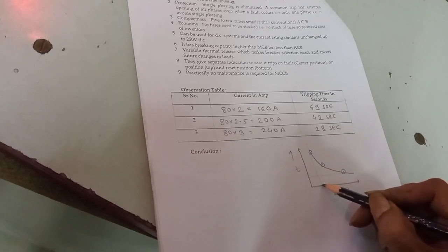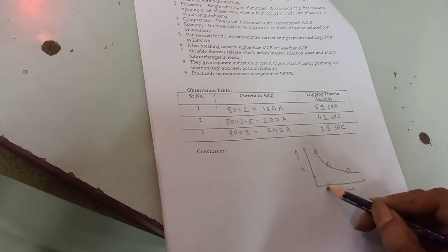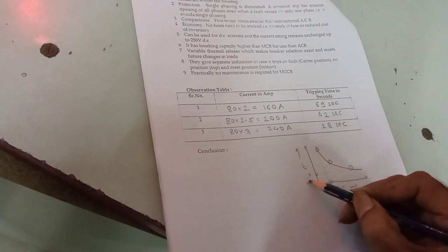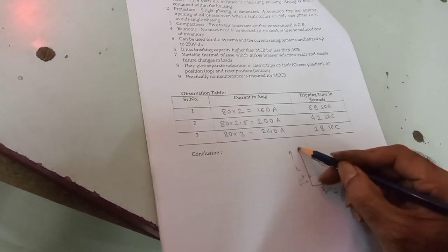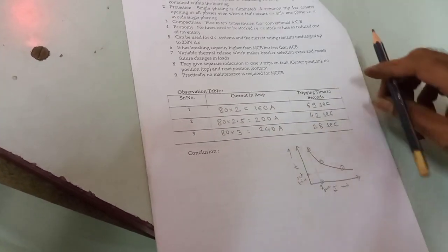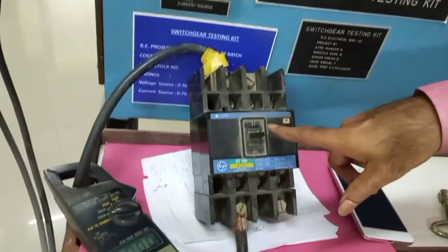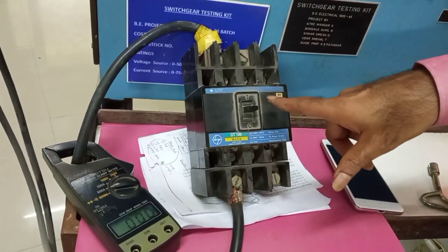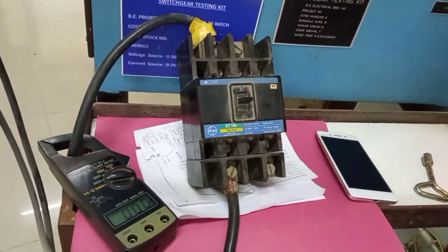As usual, when you plot 2 tangents, one parallel to current axis, one parallel to time axis, here you will get the pickup current, and here you will get the saturation time. As we have seen in case of MCB, the same will be in case of MCCB also. Okay, so likewise you have to plot the characteristic, and in this way you can see again this is in the middle position, the trip position, after passing 240 ampere of current. So in this way we have completed this experiment of testing of